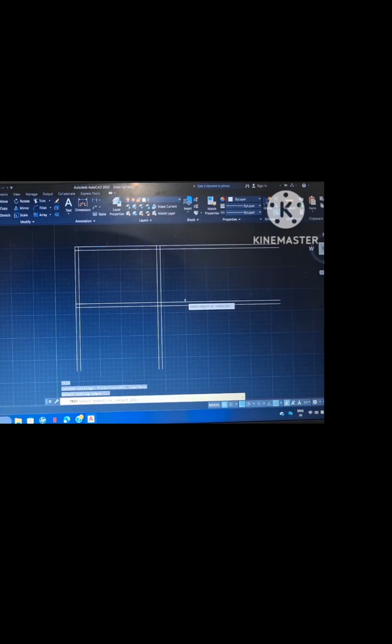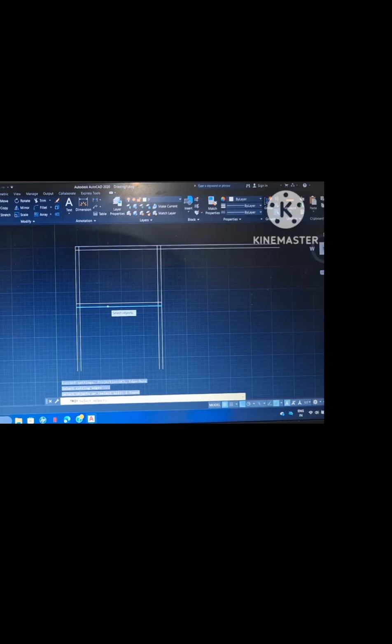Just click, then select this line. This is the cutting edge, or you can say the border of the line, the limit of the line. Then press enter, then select this line, done. Right click, enter. Now I want the same command to be repeated, so press just once enter, it will repeat the command. Select the limit of the lines or cutting edge, then press once enter, then select the lines to be deleted, this line, this line, this line and this line.